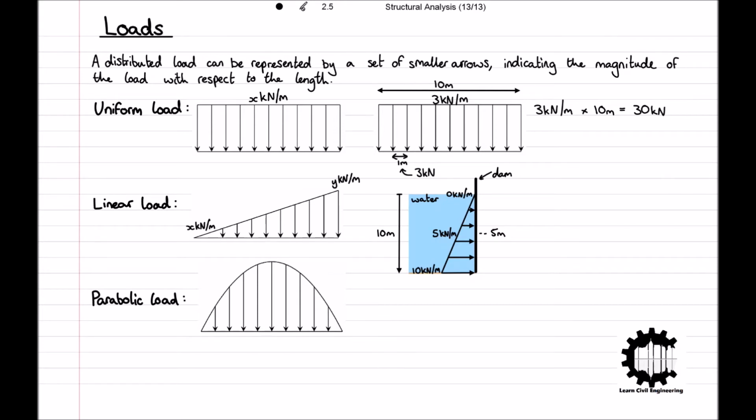Having now introduced the different types of loads we will encounter in structural engineering, we will now take a look at the types of supports. With a structure, the loads applied to various members are carried to the ground through foundations. And, for ease of analysis, foundations are represented as a function of the forces or moments they transmit, which are called the fundamental supports.